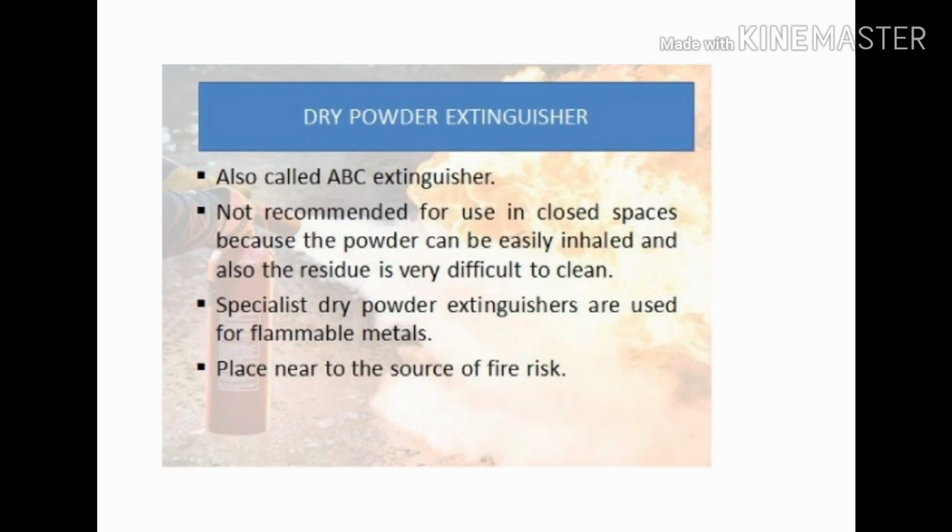Dry powder extinguisher, also called ABC extinguisher. Not recommended for use in closed spaces because the powder can be easily inhaled and also the residue is very difficult to clean. Specialist dry powder extinguishers are used for flammable metals. Place near the source of fire risk.